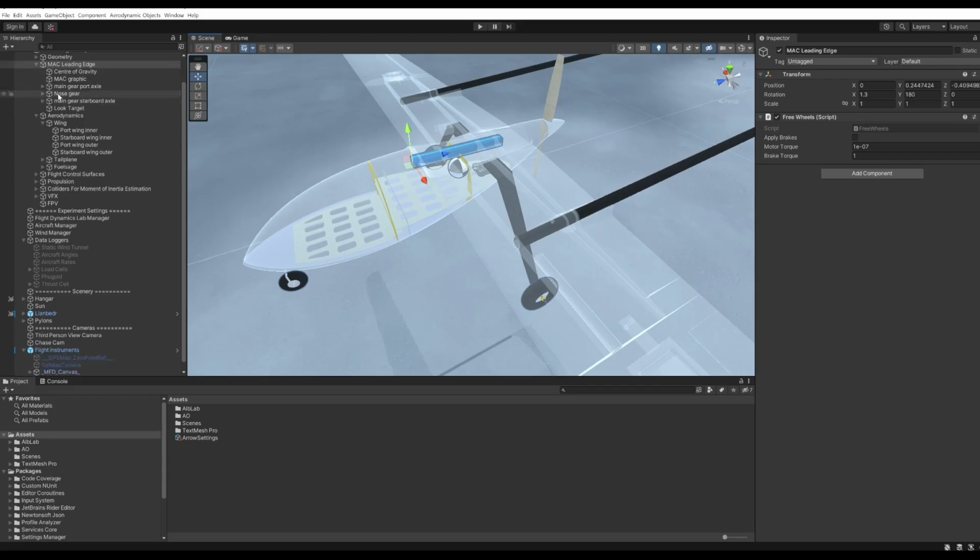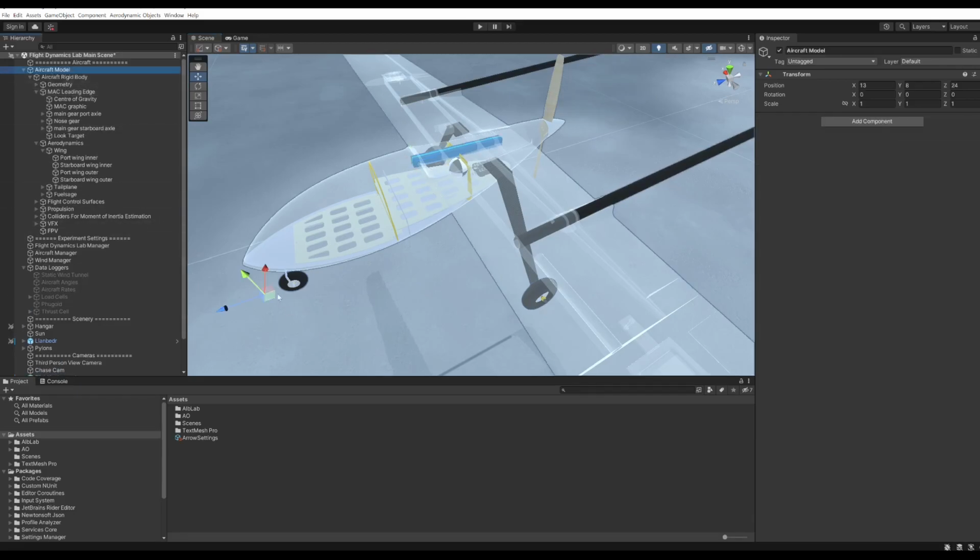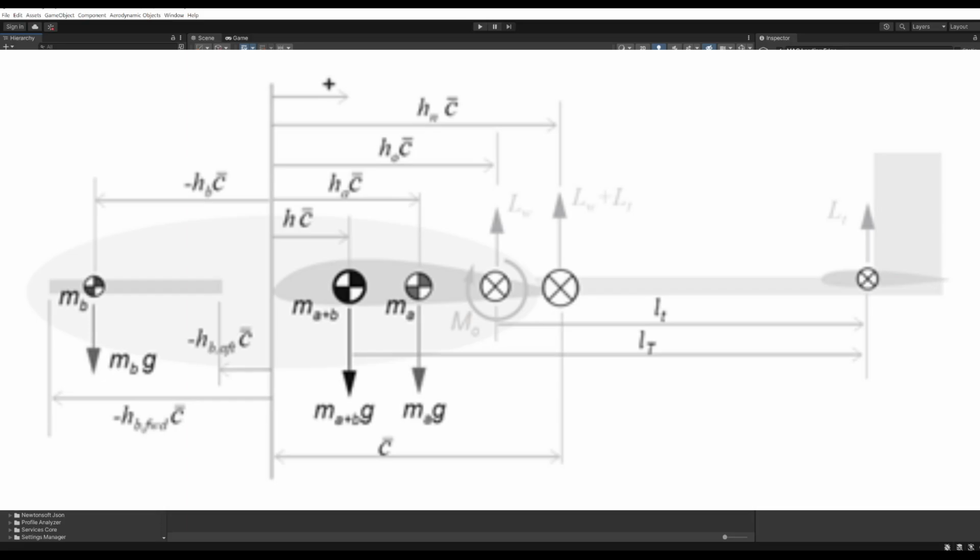And the way the geometry is set up is that the aircraft is in the world there, and this is the 0 for the aircraft, and we're in world coordinates here where Z is forward, X is to the right and Y is up, but the leading edge of the mean aerodynamic chord is then set at minus 40 odd centimeters back from the nose, so that's 40 centimeters if you put a ruler on it. But then we've done a slightly cunning thing of switching round 180 degrees in the Y direction, so Z positive is going this way, and what this means is that this coincides with the way flight dynamics distances are measured. In a sense, it's positive aft from the leading edge of the mean aerodynamic chord. So in this simulation world, the mean aerodynamic chord has been set up so that it corresponds with the textbook understanding of how flight dynamics things are measured.